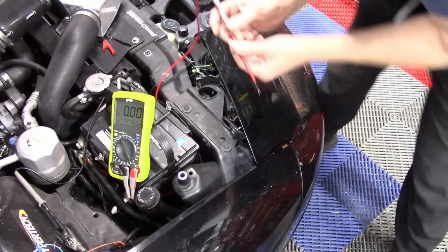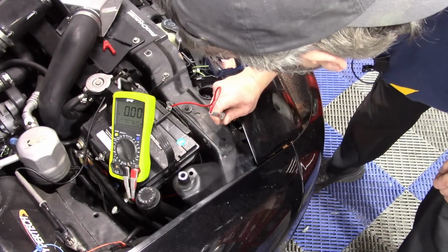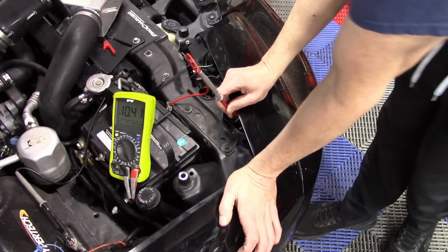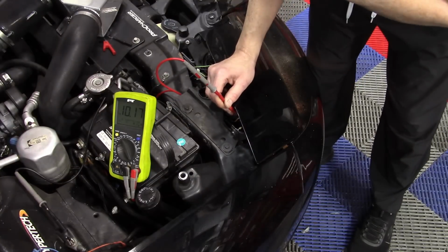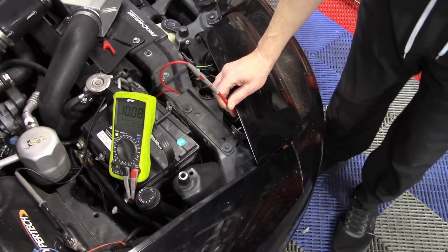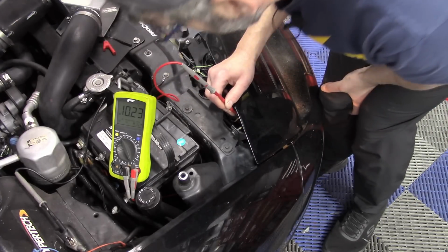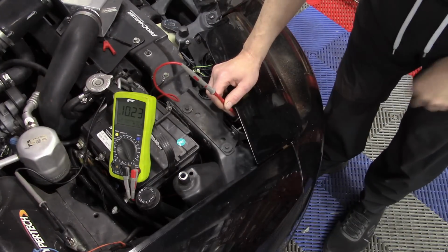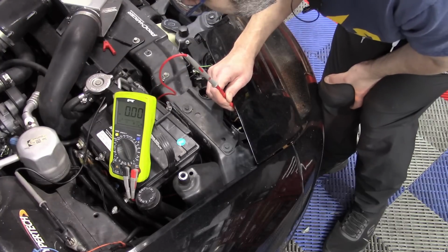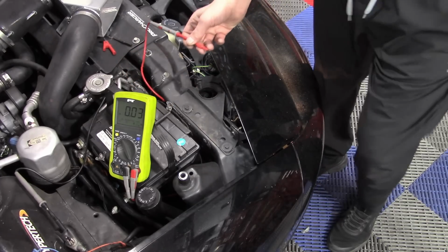Then I'm going to take my positive lead and touch it to the terminal on the brown wire. We see my battery's getting really weak here. We read 10.41 volts. Now, this is a little bit off the point, but there are two explanations: my battery's really, really low, or I could have a voltage drop on the positive side of this circuit. But we've determined this is the positive side of the circuit because we're measuring against the ground and we're getting 10 volts here. If I measure the black wire, I should have nothing, and I see nothing there. So that means the brown is positive, the black is negative.